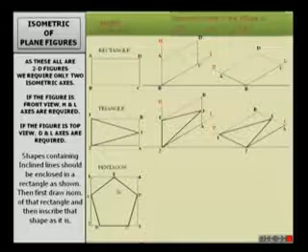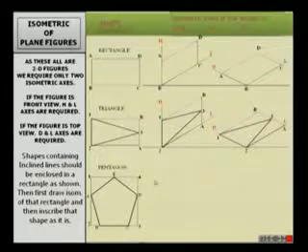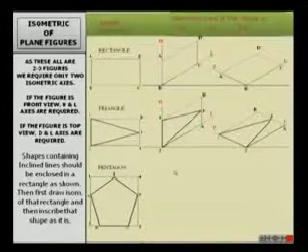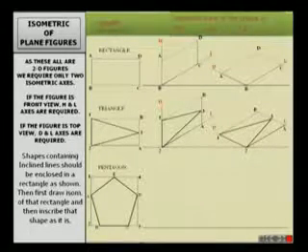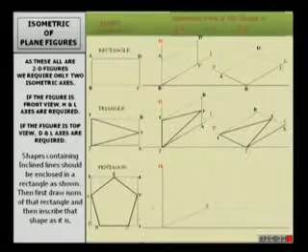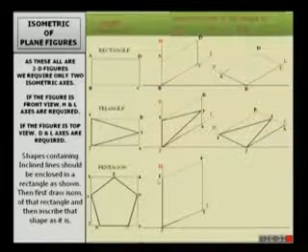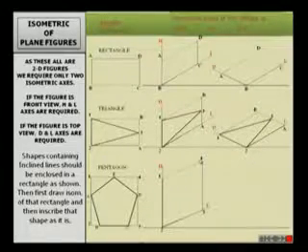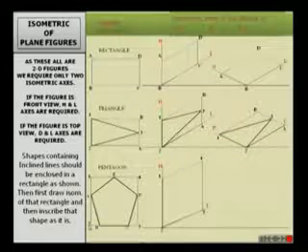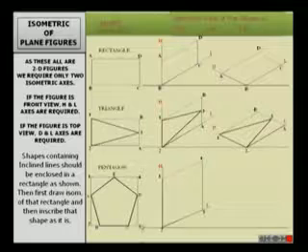So the pentagon is inscribed in this rectangle, and now we are going to produce the front view of the isometric pentagon. By drawing first H and L, we need to produce the rectangle first. So 1, 2, 3, 4 will be the rectangle. Now we know the length between A to 2 and D to 3.